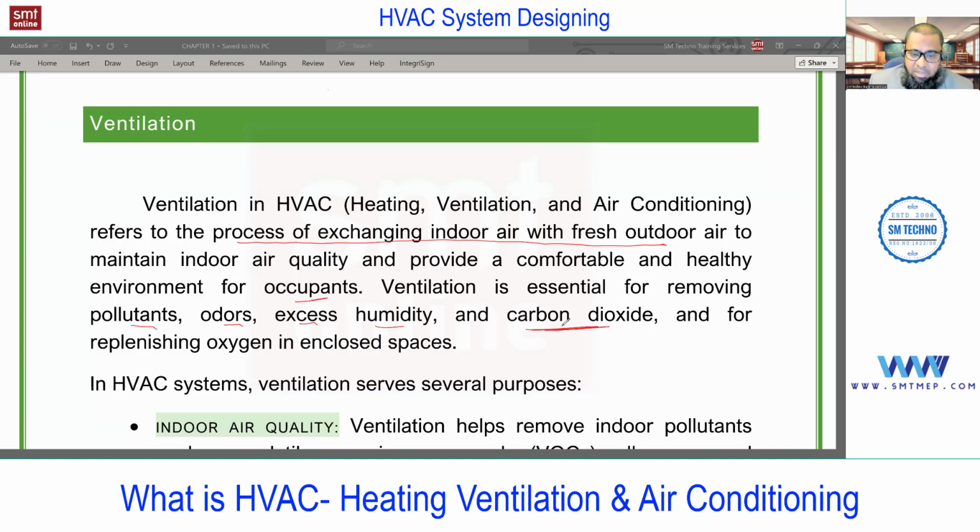So this will directly affect the efficiency of the employees in the office or the students in the school. In short, ventilation means providing fresh air from outside to maintain the quality of air with respect to odors, meaning bad smells, and to maintain humidity. But the major point is the oxygen level, to maintain the oxygen level or to exhaust the CO2. And we have different ways to provide the fresh air.